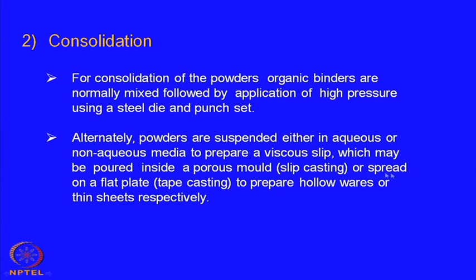However, a very similar technique can also be used for making very flat sheets. For example, in electronics, we have discussed packaging techniques and multi-layer capacitors, for which we need very thin sheets of ceramics, a few tens of microns thick.